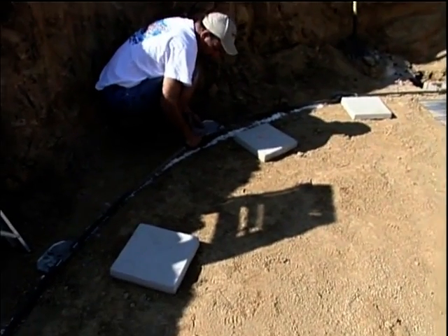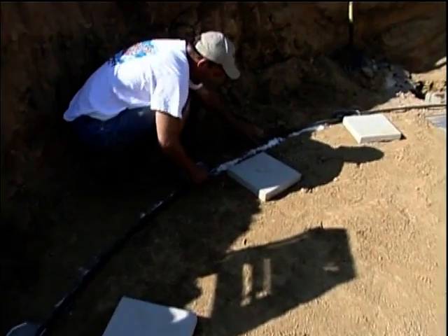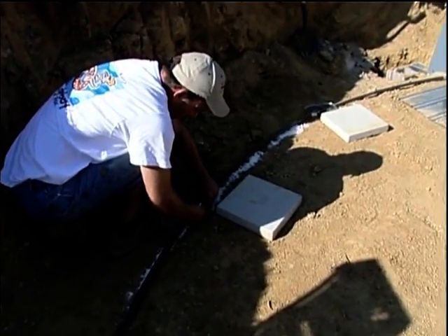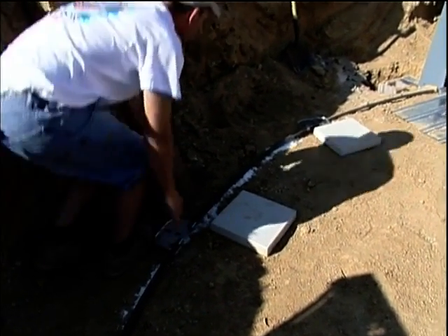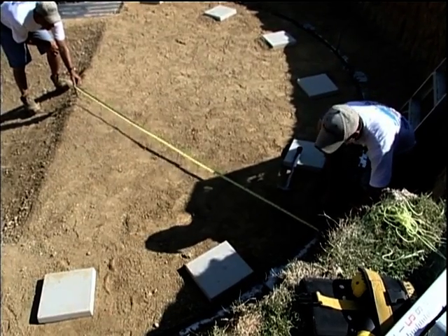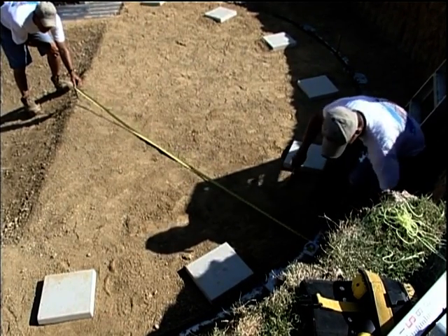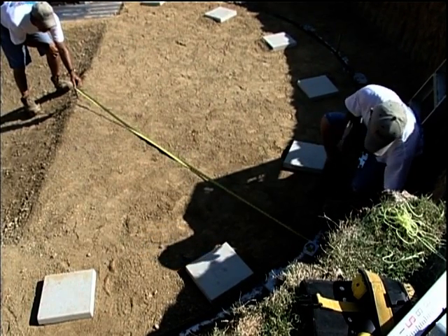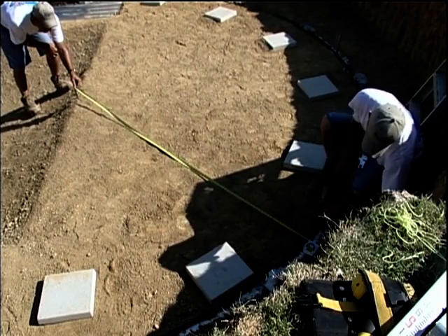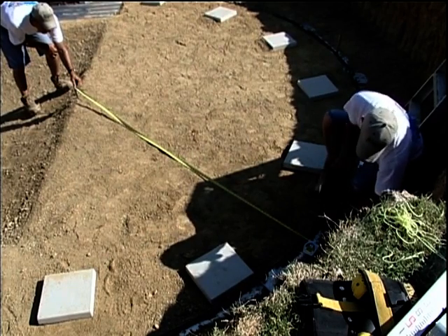Install the next bottom rail into the plate in the same manner. Continue this process until you have installed all of the bottom rails. Once all of the bottom rails are in place, check the layout dimensions. At this point, you may need to adjust some of the plates and bottom rails. You may want to stake spots to hold the bottom rails in place.